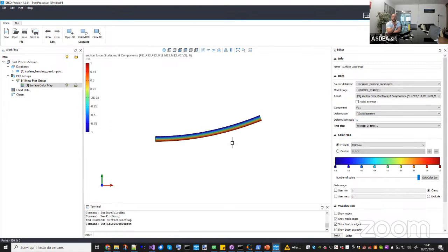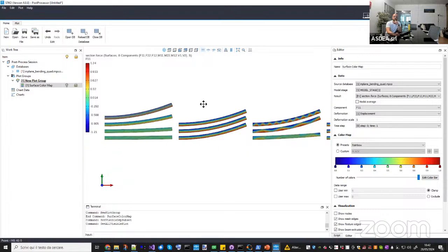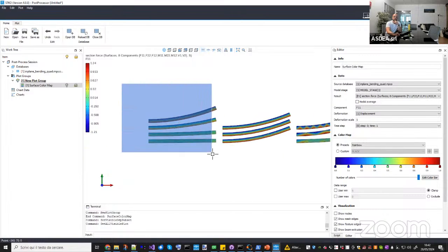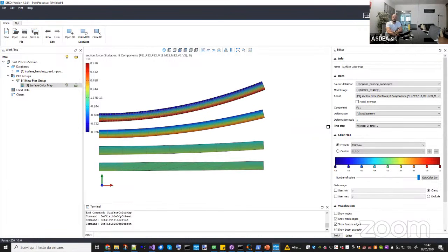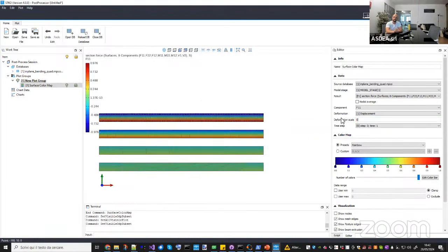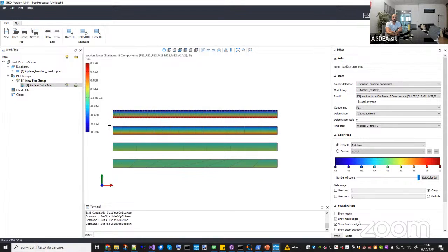So even with one single element, you are able to get the exact result, which is the same stress quality that you will have from a quadratic element, but in this case from a linear element. So you have a linear displacement distribution, but also a linear strain distribution. Now let's see how all of them behave instead. Let's start with the standard displacement-based formulation. Now, if you go here, let's go with the perfect mesh, but very coarse, okay?